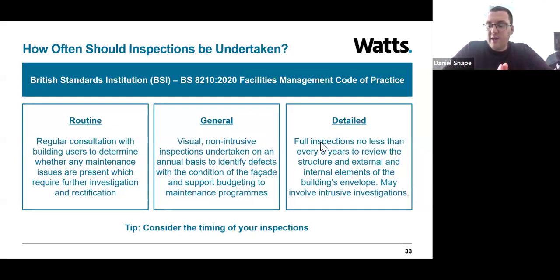If any defects are identified, it enables them to be made good before the winter, as during the winter the facade may be susceptible to more extreme weather conditions, and therefore water penetration could result in increased damage. By undertaking inspections during the spring period as well, any defects that have arisen during the winter period can be identified early and then rectified before the next winter period.